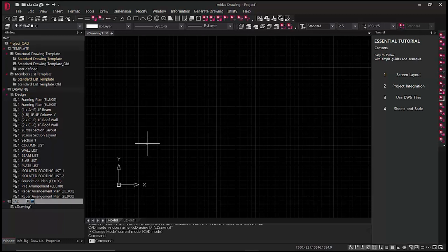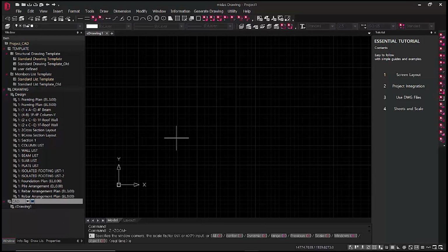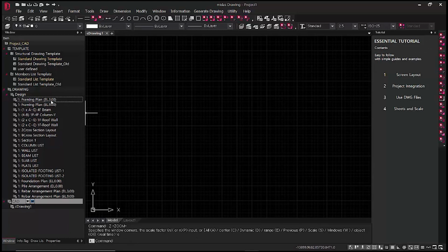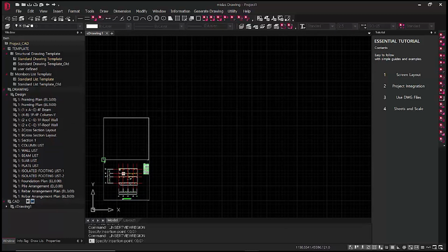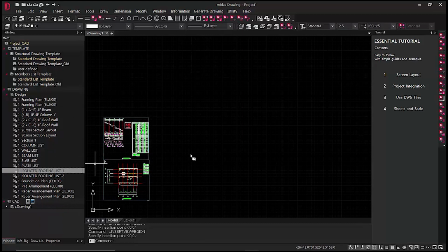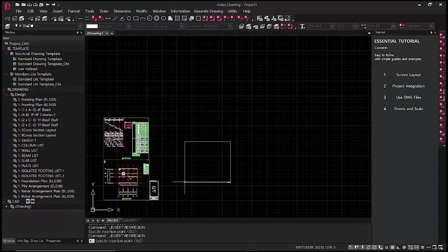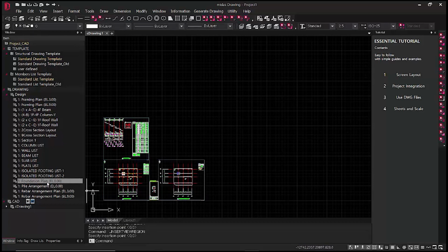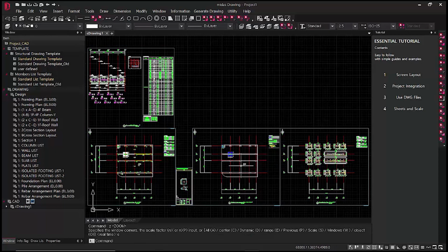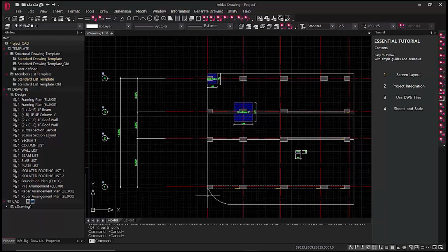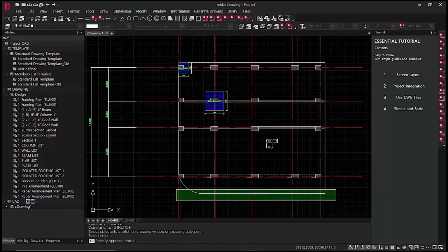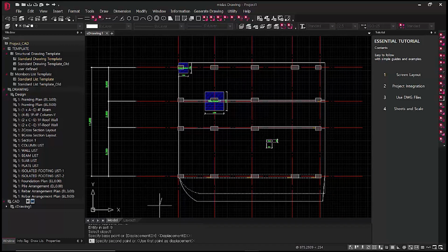The other, CAD mode, is to create and edit in the same way as AutoCAD. Okay, double-click the CAD mode to enter that mode. We will import the drawing with the drag and drop function and edit it in CAD mode. From now on, you can edit like AutoCAD: stretch, delete, and edit dimension lines.